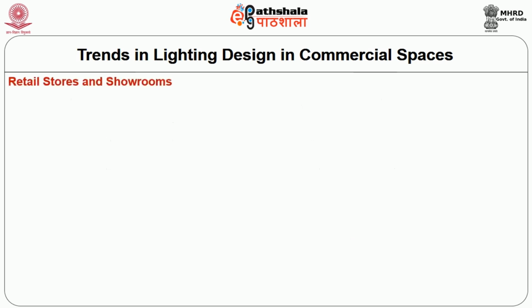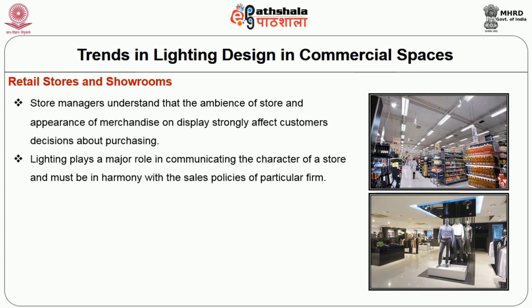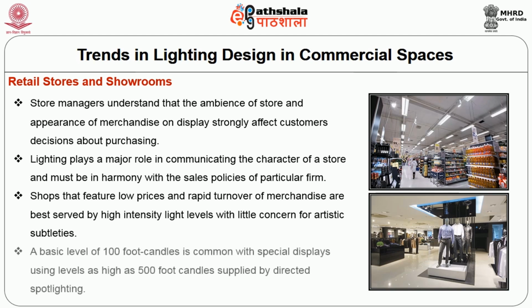The next one is retail stores and showrooms. The store managers understand that the ambience of the store and the appearance of merchandise on display strongly affect customers' decisions about purchasing. Lighting plays a major role in communicating the character of a store and must be in harmony with the sales policies of a particular firm. Shops that feature low prices and rapid turnover of merchandise are best served by high-intensity light levels with little concern for artistic subtleties. A basic level of 100 foot candles is common, with special displays using levels as high as 500 foot candles supplied by direct spot lighting.